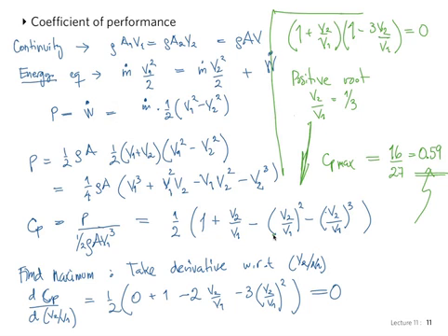And so now when we go back to our problem where the coefficient of performance was 43%, we have to compare it with that. 43% is not as far from 59 as we thought. This is the Betz limit that you were mentioning, precisely, the maximum amount of power available in the wind.